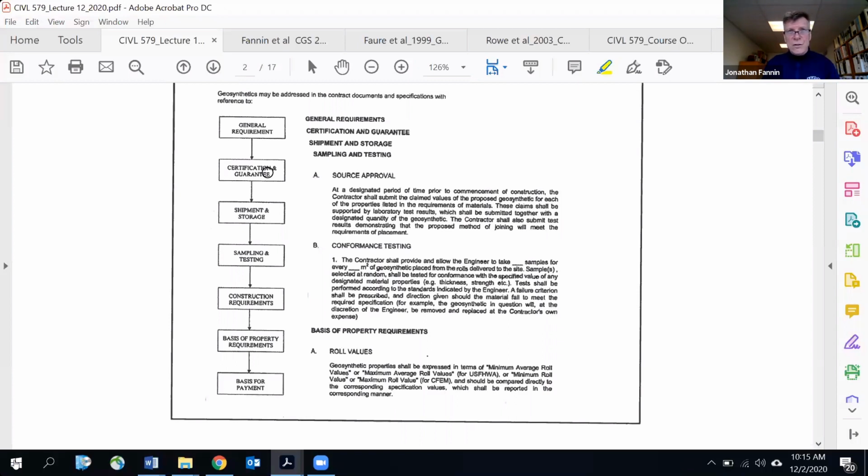How are the materials going to be stored in UV light or not in UV light prior to use in construction? Are they going to have a protective wrapping around them? When that protective wrapping is removed, are they to be stored off the ground and in the dry? Things like that. And let me just give a tangible example from the resource sector, which tends to be a little bit more of the Wild West. But I recall looking at a yard of geotextiles being stored for use in forest road construction.